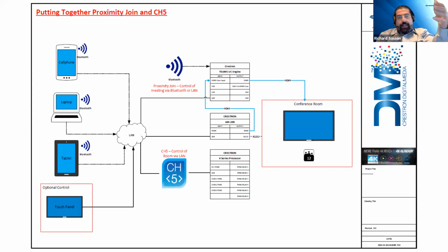Maybe you could talk about how with AM200s or with HDMD 400s, you can configure a system to be controlled via CEC or 232. Yeah, in either of those two, you have an onboard capability to do 232 or CEC. CEC I enjoy, but CEC is dependent upon the display itself. It is obviously a standard across multiple platforms, multiple manufacturers, but the manufacturer does have to support the CEC for that to be able to be utilized, where 232 in a lot of cases is what I would call old faithful. It's something that we always kind of rely on. Being candid, a lot of us have used 232 forever.